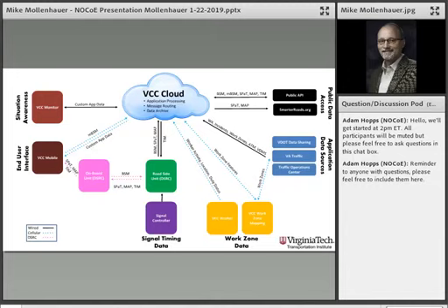To support the development and the creation and deployment of traveler information messages, we also tap into VDOT's data sharing sites. This is the same data sharing system that powers their 511 system. So we take all the traffic incidents, work zone definitions, active traffic management data, variable dynamic message signs. We pull all those into our cloud, turn them into the appropriate messaging standard. In this case, that's typically a traveler information message, and then we broadcast them back out either through the cellular interface or through the roadside DSRC units as well.